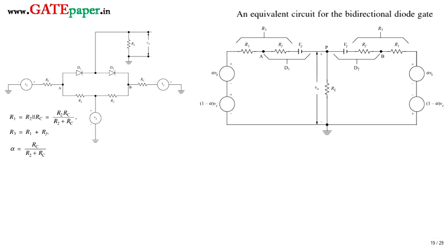Okay, and we already checked this one. If no input signal is applied during the transmission period, V0 is equal to 0 when Vs is equal to 0. That is, when the diodes are forward biased, V0 is equal to 0, it is independent of control voltage,